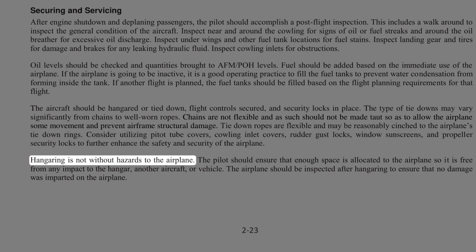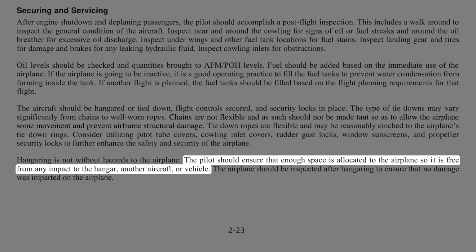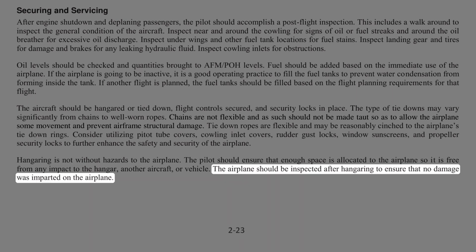Hangaring is not without hazards to the airplane. The pilot should ensure that enough space is allocated to the airplane so it is free from any impact to the hangar, another aircraft, or vehicle. The airplane should be inspected after hangaring to ensure that no damage was imparted on the airplane.